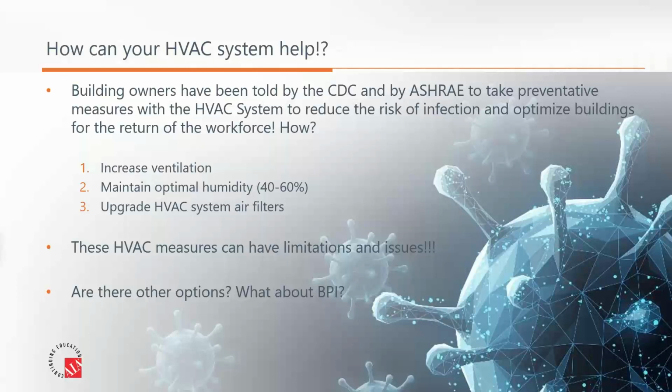And in other cases, when we do put MERV 13 filters in, there is an additional pressure drop associated with that. But then when you also look at the size of the bacteria and virus contaminants, you realize that they don't naturally get filtered out 100% in that type of filter. So we'll talk about that a little bit more, but that's something to think about.